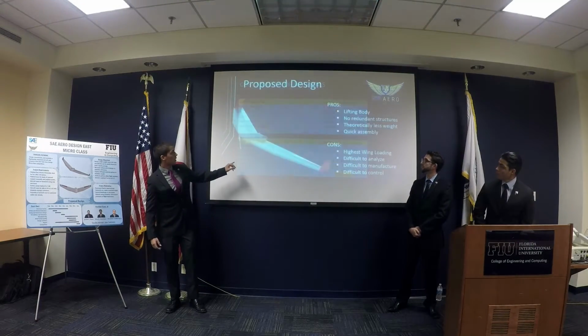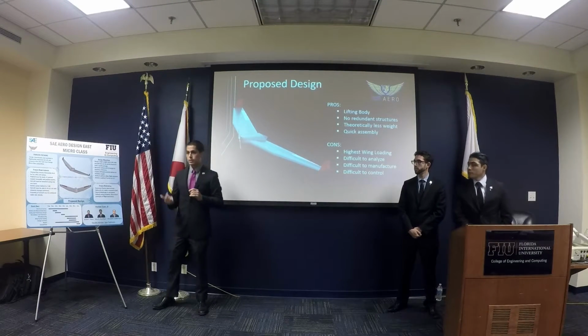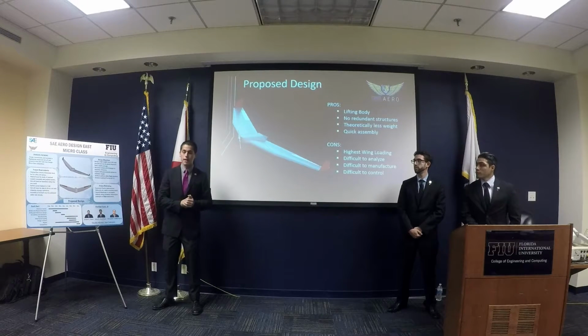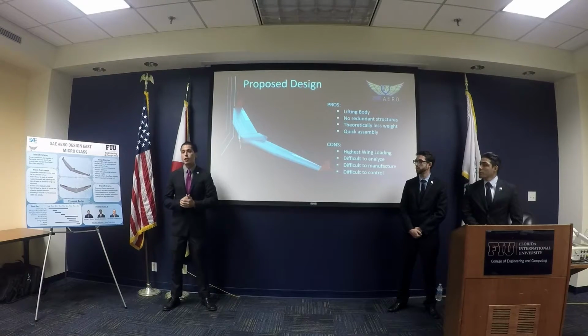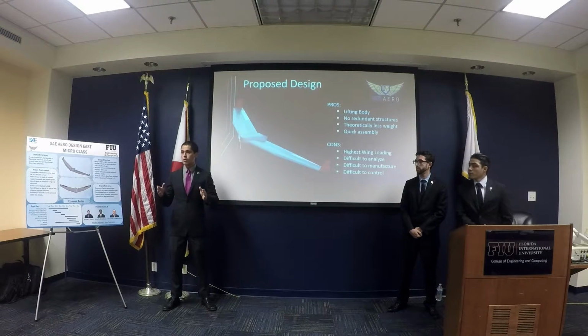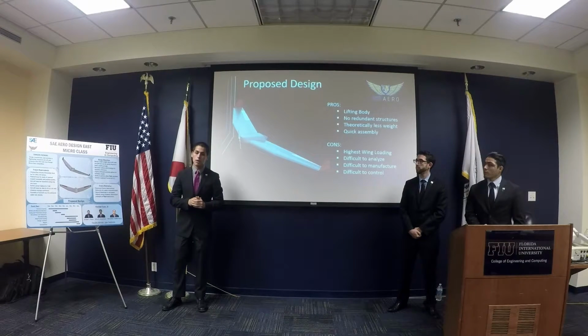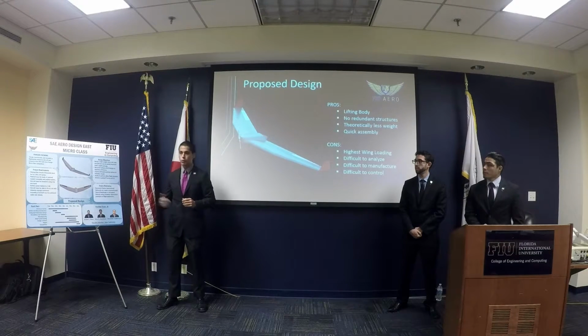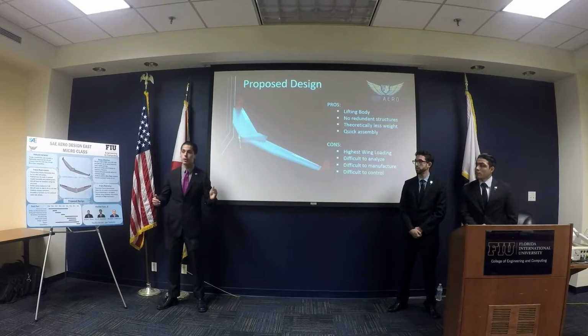We're also thinking, if you can bring back the slide of the final render. Well, this is a fuselage, right? On a flying wing, you have the center of pressure where your lifting force is acting, and your center of mass after the payload is at. This fuselage is not going to be a one-to-one fit of the payload. It's going to have some shimmy space, so we would be able to move the payload forward or backward depending on the characteristics of flight. Also, as part of the competition rules, the wing has to be flown without payload and with payload. So we do need some sort of rail where we can adjust the weight, and therefore we'll have stability at 6 pounds and we'll have stability at 1 pound.